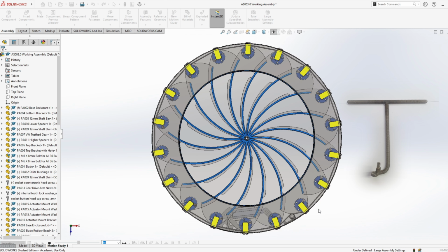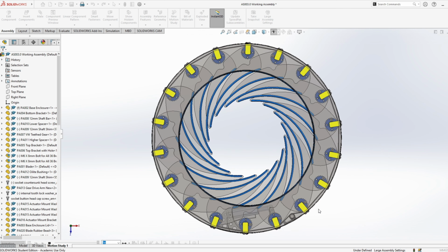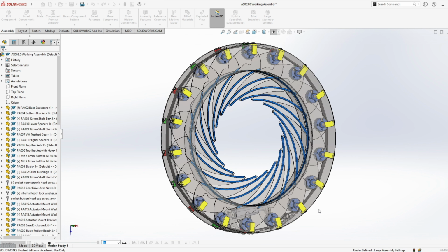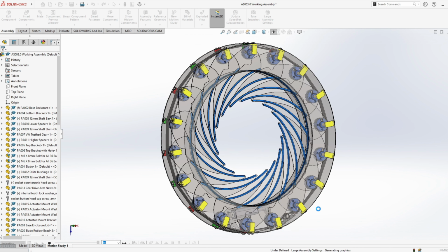So basically you position the special tool down between the blades from the interior side. Then you proceed to slacken the two bolts seen there at the bottom of the blade below the gear, and then you move the blades into position. You time the blades, then you retighten these two bolts to finish the process.